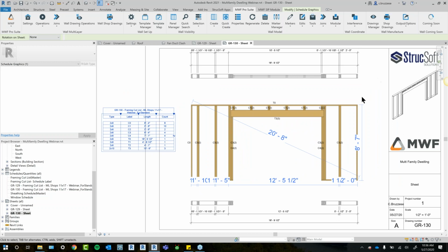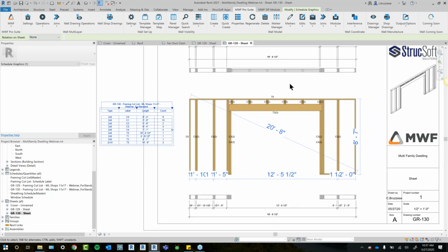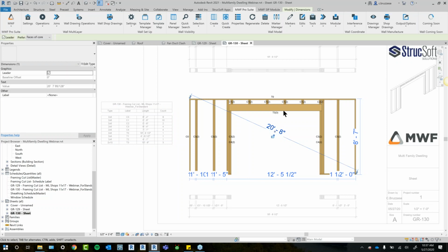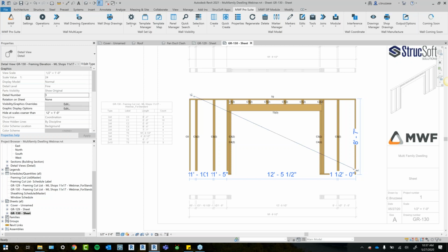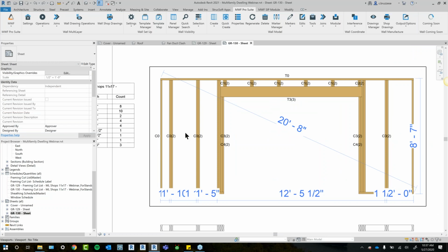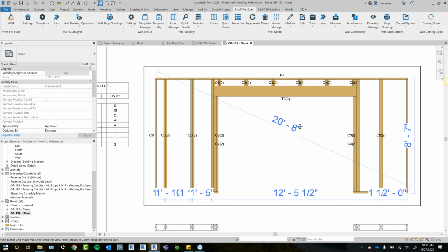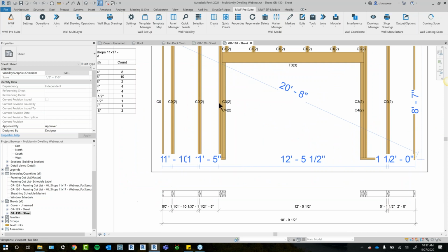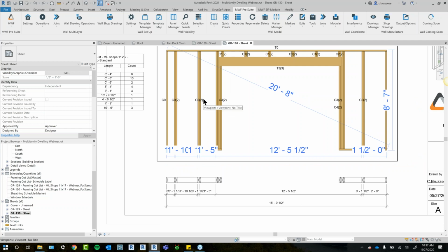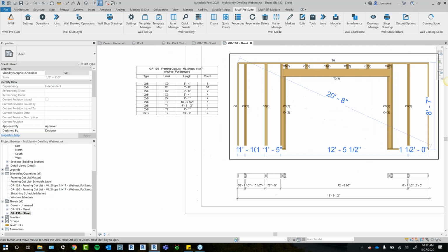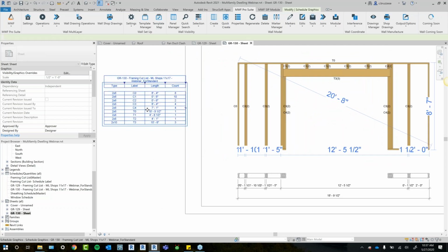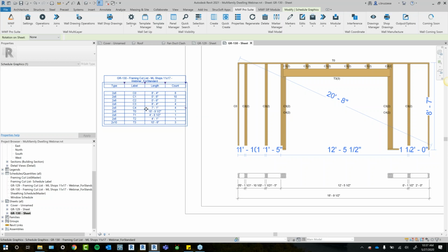So for this particular panel here, we've got our top and bottom views. Everything's dimensioned. I could maybe forego the style and use one that's a little cleaner, but you could always go back and set that up in your shop drawing settings. Everything's labeled, grouped together. So this is where that proximity grouping comes in. It can add the extra number in the brackets instead of having individual labels. It just makes it look a lot cleaner. And then you've got your general Revit schedule here as well.